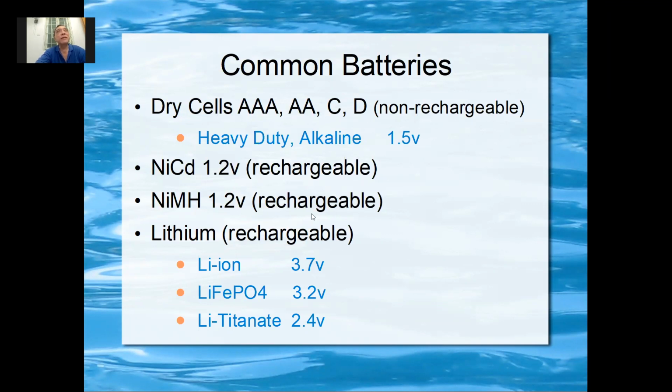Okay, and then a better one than nickel cadmium is the nickel metal hydride. This is 1.2 volt. In the early years, they used this for cameras. Because when you use a flash, if you use an alkaline battery, you flash 30 times, gone already. But with this one, you can go maybe until 60 times. But lithium can flash 100 over times. You know, better, more energy.